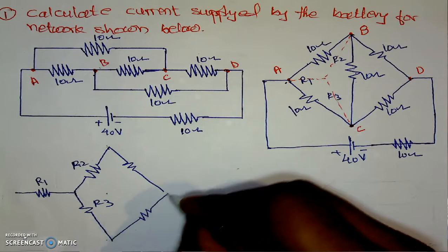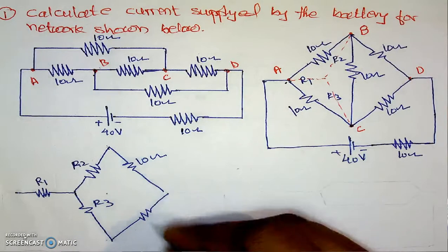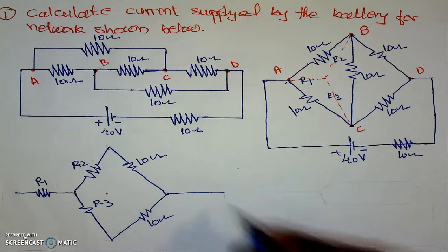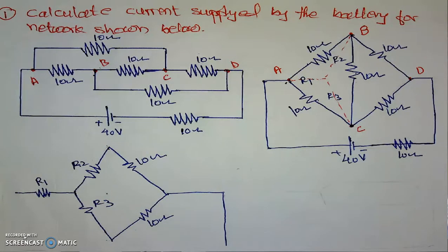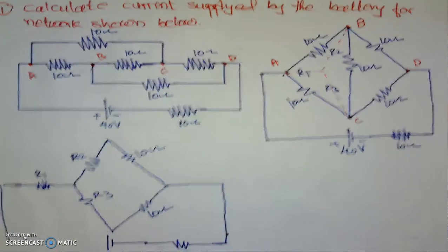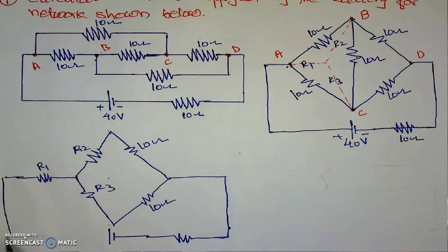Means here this is the same, 10 ohm as it is. Now here this will be the circuit diagram, and then we can minimize the circuit by using conversion, that is, by using series and parallel combinations. Yes, this is again plus minus, this voltage is 40 volt, this is 10 ohm.